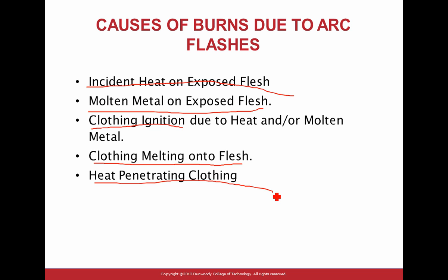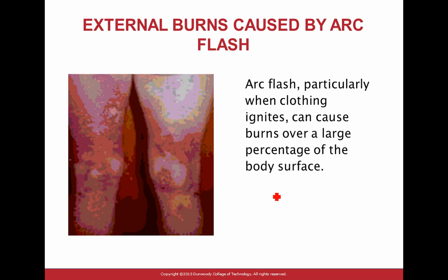Under certain circumstances, guys, if you're in category 4, they want you to wear underwear that cannot ignite when you work on that. I'm not kidding you. An underwear and a t-shirt, it goes down deeper. So it's not just what you wear on the outside. You have to wear layers and underwear that doesn't ignite, category 4. So not just what you put on yourself.